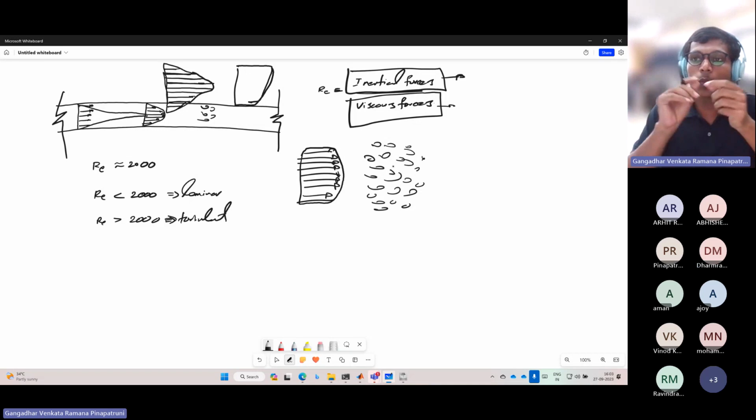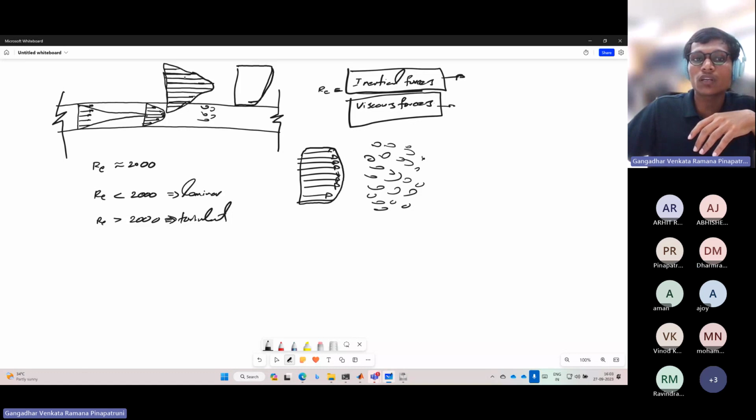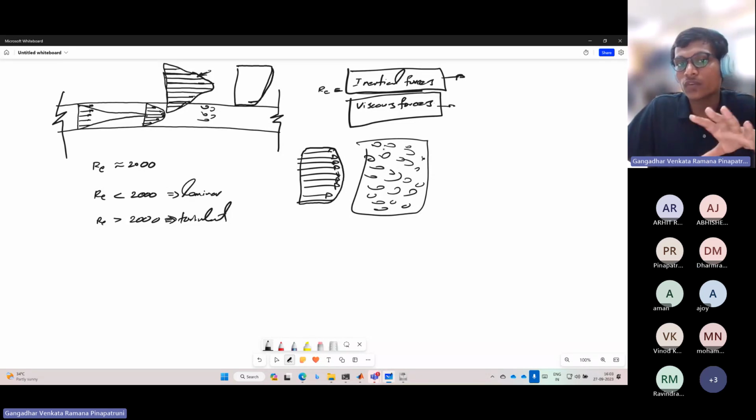Their movement fluctuations are like, if you see boiling, molecules or atoms moving very randomly at high speed, right? Exchanging their momentum with other particles at high speed. Here, the exchanging of momentum is not possible in the way we are seeing here. So this is what is dominated by the inertial forces. If your viscous forces are less and you are dominated by the inertial forces, then you will see this kind of phenomenon. This is why we differentiate between inertial forces and viscous forces.